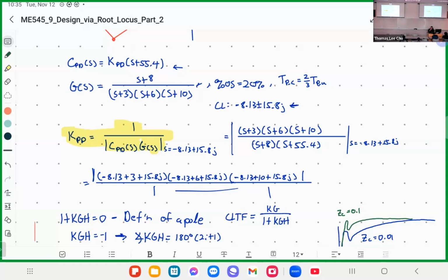And finally, one last comment about the homework is that when you're doing your PID controller design or your lag lead controller design and you're trying to design it for peak time, you expect a reduction of peak time, but you actually get a really long peak time. That's common. Because it's an approximation, it doesn't always work out. Let's say you're shooting for a 1.3 second peak time and you get a 20-second peak time.